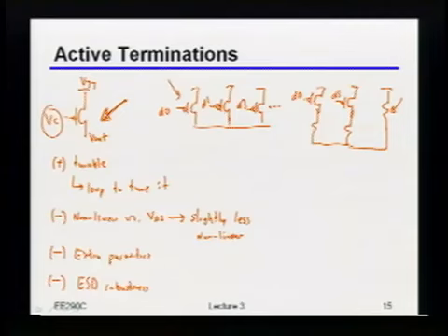So here what I'm trying to do is decouple: let me get something that is kind of close to a best guess, and then only pay the extra parasitics for tuning around that nominal bias point, so to speak. Okay? So this also turns out to be less nonlinear, simply because most of your resistance should still be coming from that nominal leg over there. It turns out also to have a little bit less parasitics for kind of the same reason.